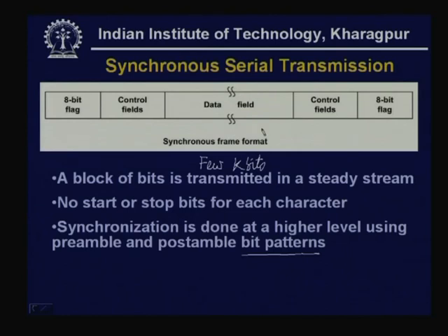Now, here one question arises. We have told that the clocks of the two ends must be fully synchronized. How can it be done? One alternative is that a separate line can be used for sending the clock. Then at the receiving end, that clock will be used for receiving data, but that is not practically feasible unless two systems are located very closely.